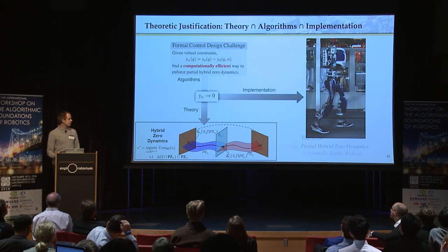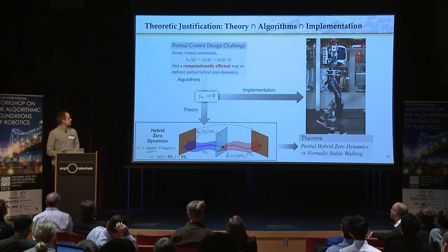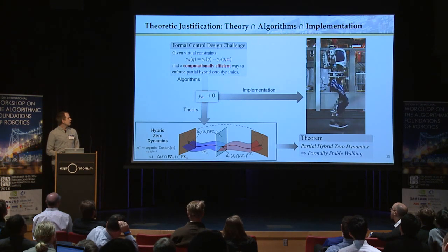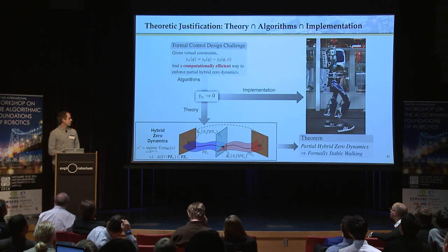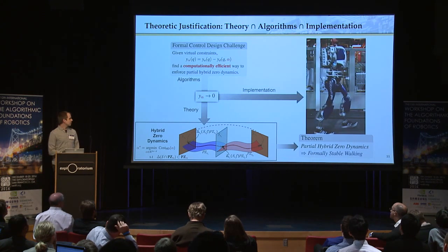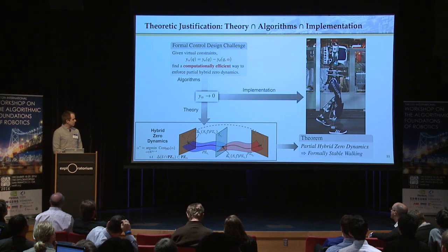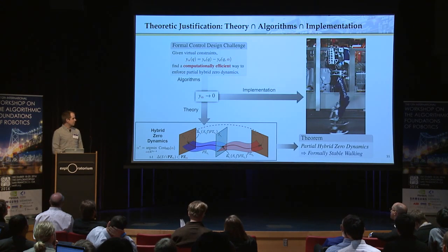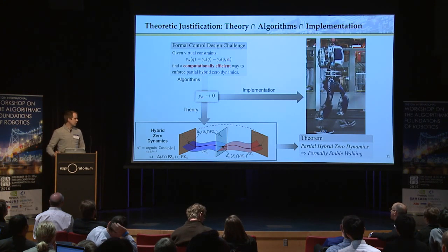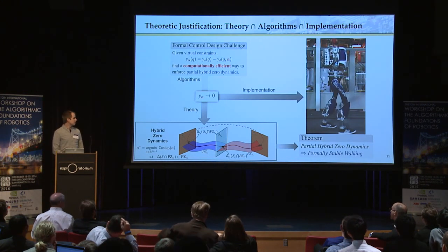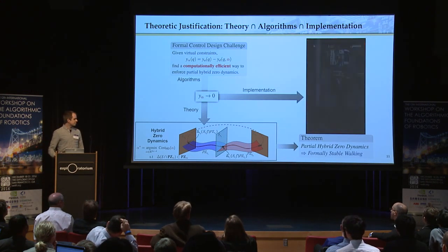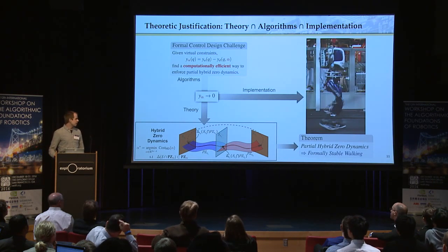And the problem really then becomes designing these gait parameters alpha such that we have this hybrid invariance. We'd like to design these parameters so that we evolve along this continuous zero dynamics manifold, and when we strike and have an impact, we return nicely to our fixed point. So we're invariant through the impact map.